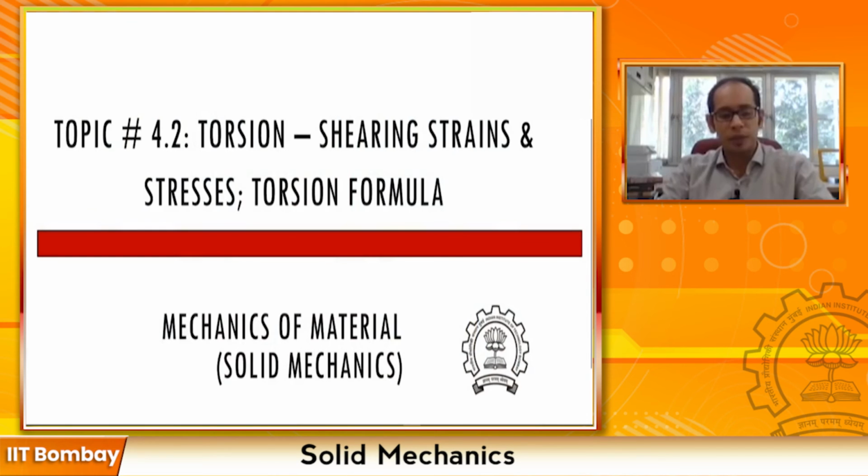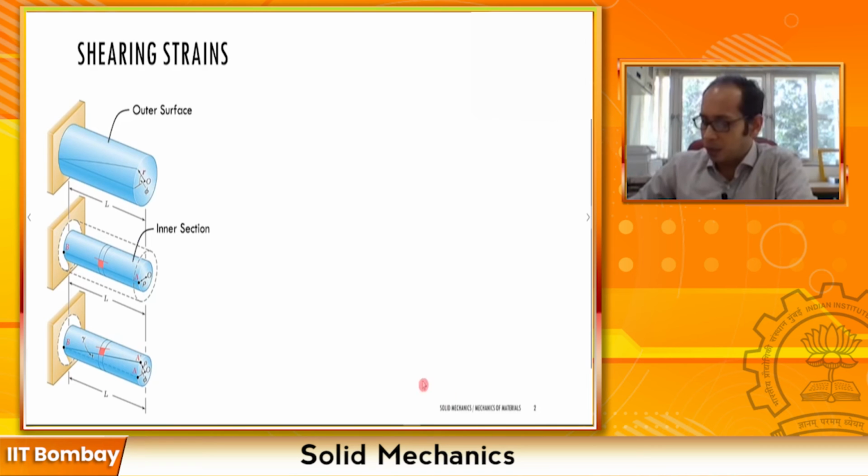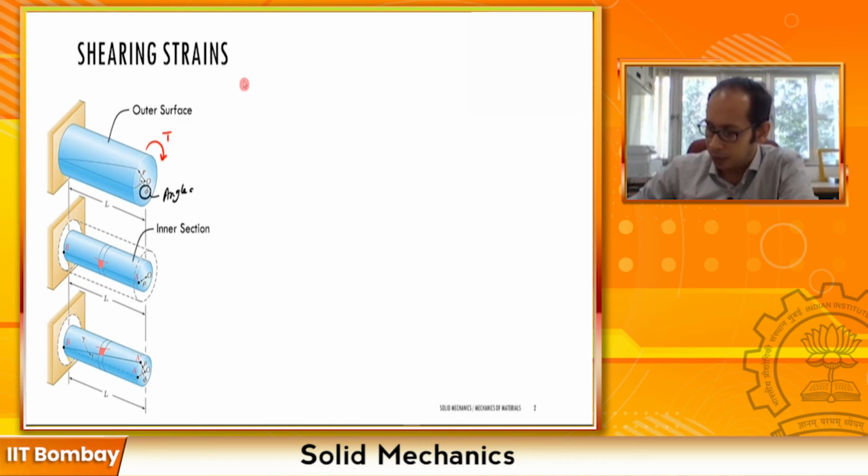Again, where we left off, we are looking at the circular shaft that we had seen before, and in this circular shaft, this was a horizontal line which was there previously. After you have applied a particular torque, let me indicate the torque over here, I have applied a torque like this, T, so the points are moving relatively up. This point which was over here has moved over here, and has inscribed an angle. So this phi, remember, still remains as your angle of twist. Let me just write that down. This phi over here is still my angle of twist.